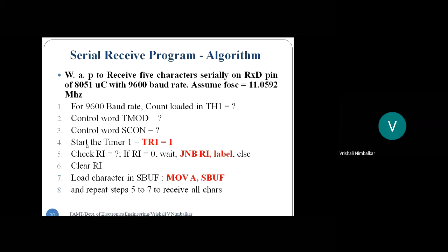Okay, so when all the 8 bits are received, that indication will arrive on the RI flag. RI flag will be set. We will clear the RI flag and then pick the character from SBUF. Hope you are getting me, students.